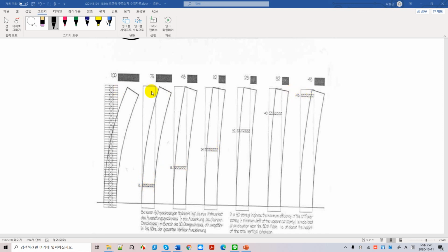And you see the deflections. Deflection decreases as your outrigger is located towards the top. Maybe your smallest deflections occur when you have the outrigger near the top of the building, whereas you have significantly bigger deflections when you install your outrigger at the bottom.